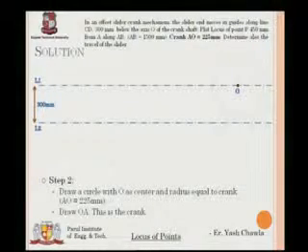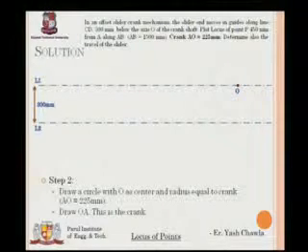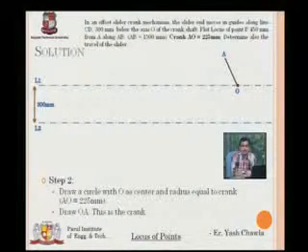Now what is my next step? Now I have my O, so I will draw the crank circle. As we did in the previous question, I need the crank circle because I should know how far my crank will be and how it will be rotating. So I will take my radius as AO, that is 225 mm, which is equal to the length of the crank, and I will draw a circle. Now, I have my crank circle, so I'll take any position and draw my crank. AO is my crank that will be rotating.